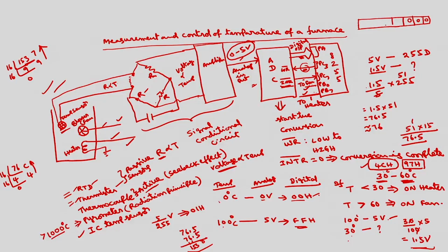This is port C upper. We are going to take this as an input port, so 1. This is port A. Port A we are using as an input port, 1. Mode selection for port A, I am taking mode 0, and this is for I/O mode, this is 1. So it will be control word 98H.